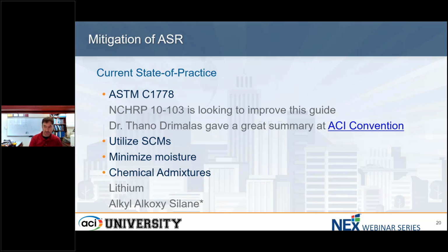We might use an integral waterproofing agent, or we just might try and prevent use of suspected ASR active aggregate in conditions where the concrete would get moisture exposure. Now, jumping back to SCMs, a lot of concrete made nowadays already has SCMs, so that's great. So we're either directly or indirectly mitigating a lot of this.